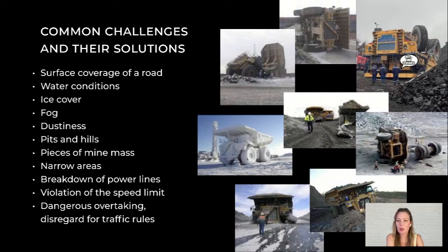Next, water in the quarry. We need a multi-stage approach to manage water, starting with in-well dewatering, followed by contour dewatering, and finally in-pit dewatering. It's crucial to minimize water flow into the quarry and control any that gets in using trenches and sumps. And the next slide will show how water affects the wear of heavy-duty dump truck tires.